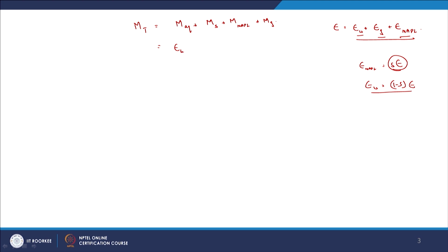So, I need the volume of water. So, that is porosity, the volume occupied by water, right, times the concentration in the water, right. So, C is the concentration in the water plus mass adsorbed onto the soil, right. So, how do I get that? As we know, bulk density of the relevant soil times q, and what is q? By now we should be able to understand this. This is the mass of contaminant per mass of soil, right. So, more or less the concentration adsorbed onto the relevant soil, right.